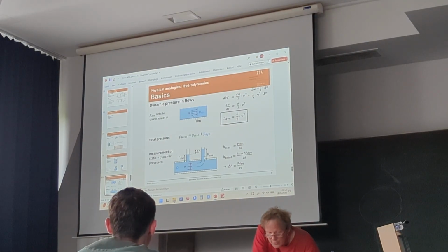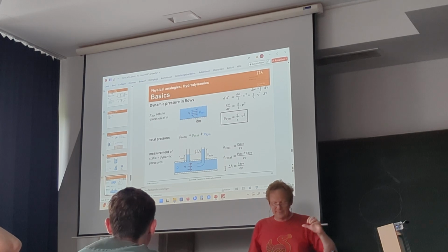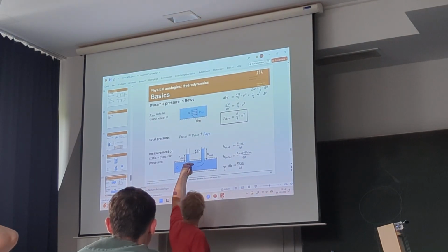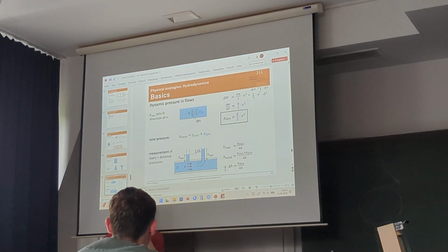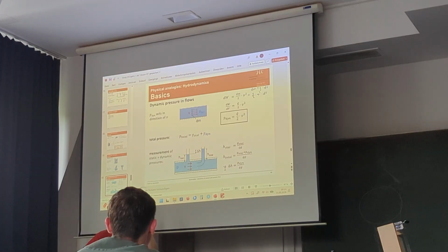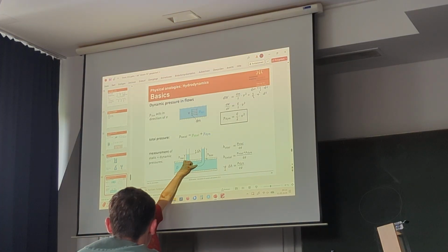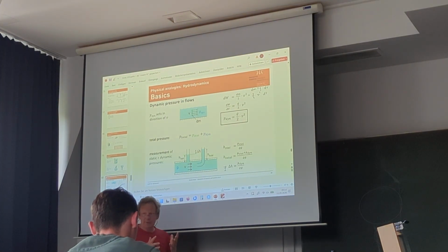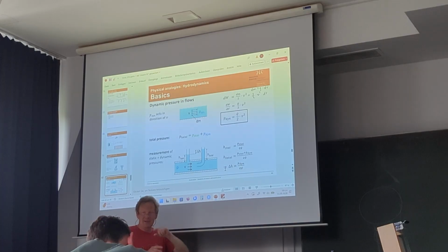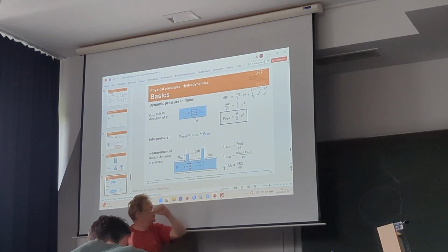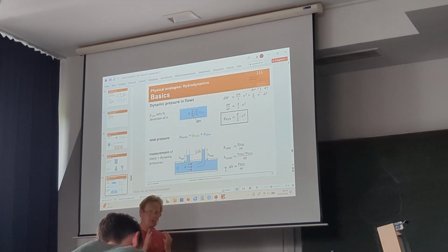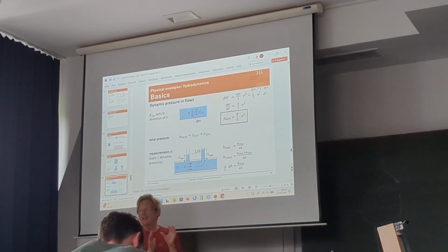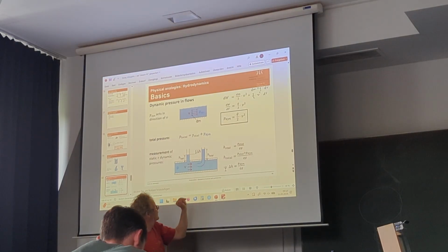The second one is also a pipe and opening, but this is bended. And it should be a very smooth bending. So that means here at the inlet, we can really feel both. We can feel the static pressure, but also the dynamic pressure. Now this is carefully redirected upward. Let's assume we have no losses, which is not true, but let's neglect losses here due to the bending.